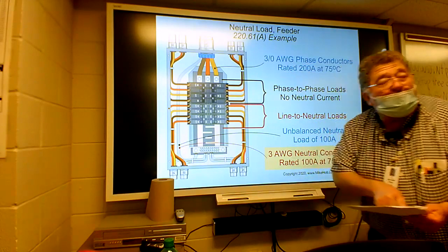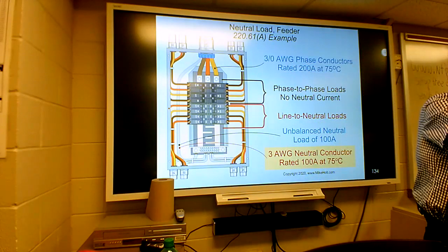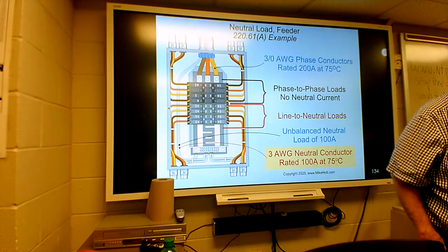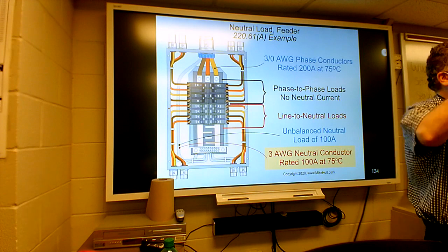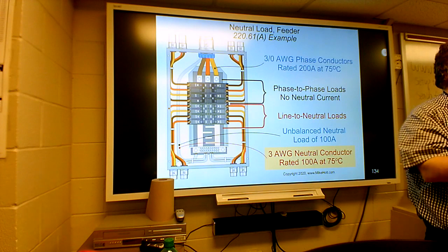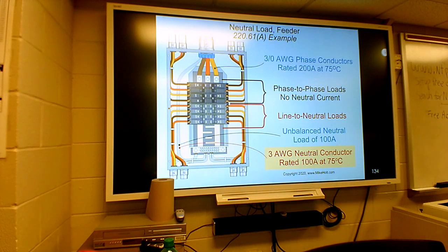So for 200 amp, what size wire is it, guys? Do you see it on your chart? Okay, what do y'all see? 3 aught. If it says 3/0, that's 3 aught. And the word aught, if you look here,